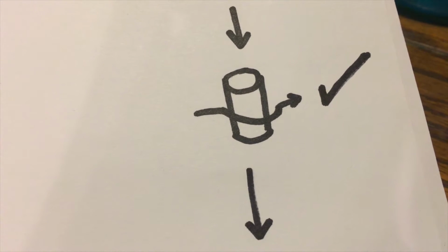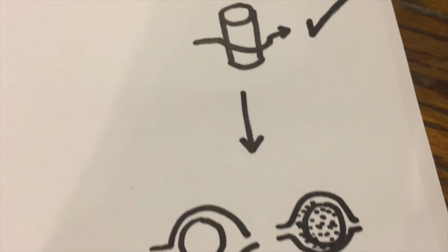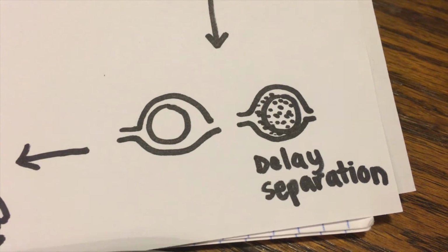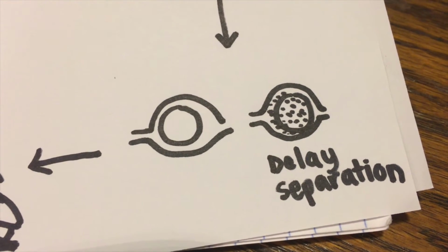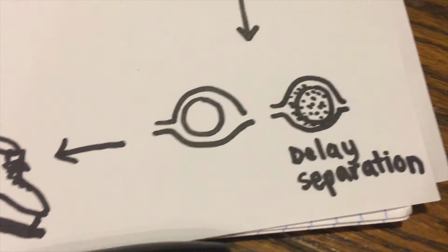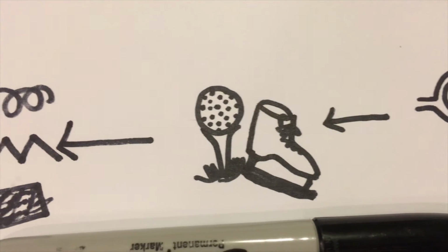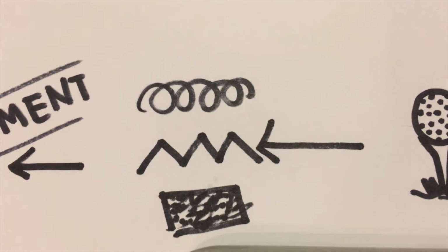avoided. It is often beneficial to force transition of the boundary layer to turbulent in order to delay the separation point on the cylinder. Doing this reduces drag by minimizing or eliminating recirculation zones on the body that increase drag. This method is often used in golf balls, sailplanes, and speed skaters. Commonly used methods to induce a turbulent boundary layer during experiments are zigzag strips, sandpaper, and circular wires.